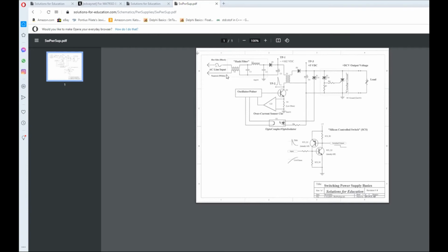So here we go. First of all, you have a basic power supply in the front end of this. All it does is take the line voltage. And by the way, you'll notice this unusual aspect here. This is called a hash filter. The reason it's called a hash filter is because these things make a lot of noise. You don't want this noise passed through and getting up into the power line, and all throughout your house you have all this horrible hash because of your power supply for your ham rig. And it shows up in everything. Well, this is a special hash filter, not simply a rectification filter, but a hash filter to keep this from getting out on the line.